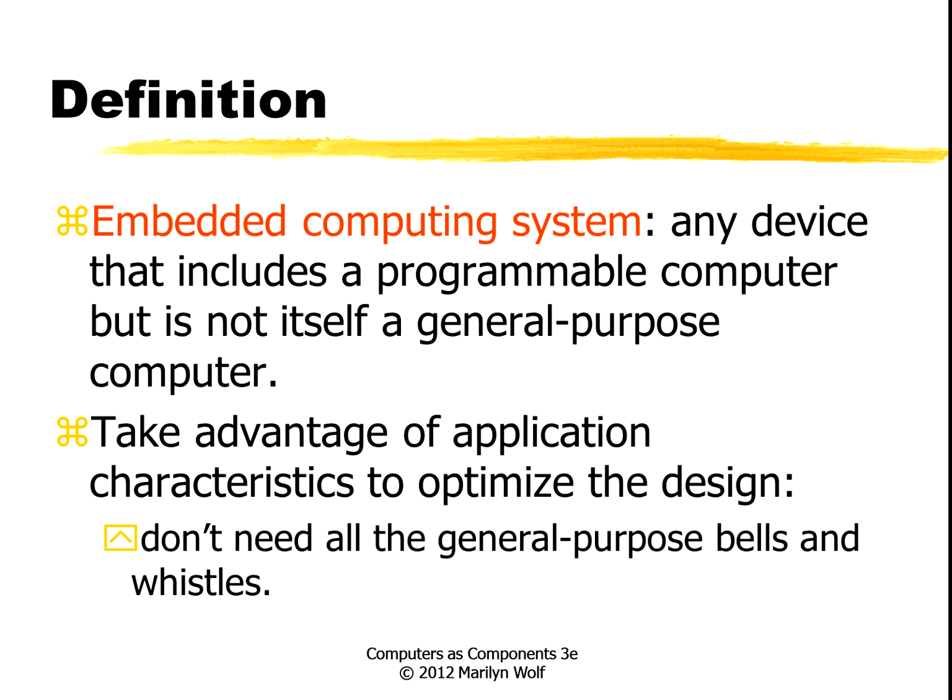Embedded computer systems have to interact with the real world, and that means we need a lot of specialized techniques in order to design them. One of the things that we do is take advantage of the application characteristics when we design the system. So we may not put in all sorts of features that we don't really need. When you're dealing with real time, when you're dealing with low power, putting extra things in may make it harder for the system to do what it has to do in the time and the energy it has.